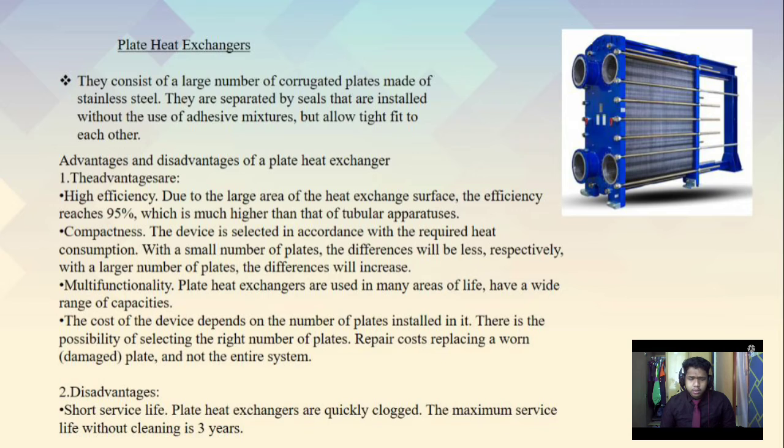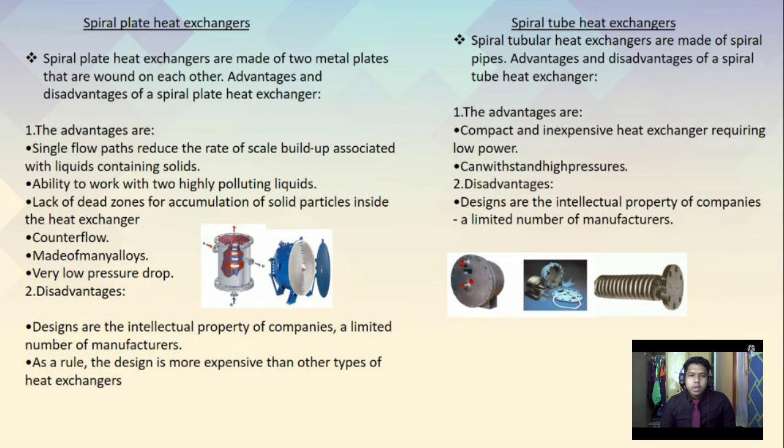The disadvantage is, first, short service life. Plate heat exchangers are quickly clogged. The maximum service life without cleaning is 3 years. Next, spiral plate heat exchangers. Spiral plate heat exchangers are made of two metal plates that are placed one on each other.